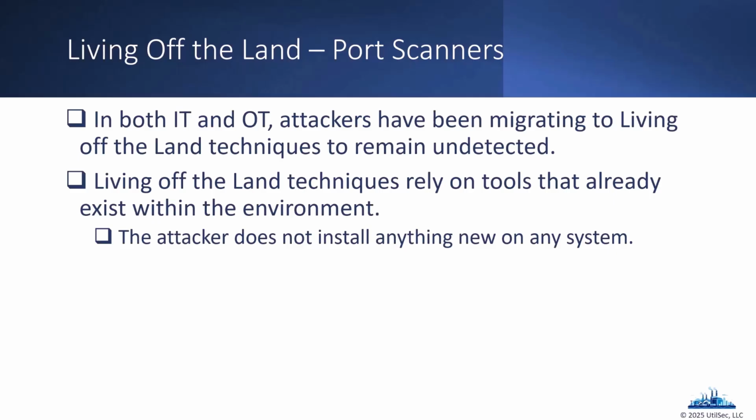They found what was described as a bridge between IT and OT. I don't think they've still publicly disclosed what that is. So they moved from IT into OT. And then they're sitting on the Windows machines on the OT network and found the web interface for their SCADA manager where they could log in with easy to guess credentials, find the interface, the HMI that controlled the breakers for the power. And they just flipped the breakers to turn off the power, and then they wiped all of the machines as they always do.